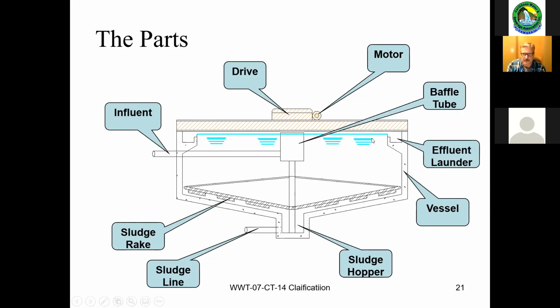And your baffle tube, which is in the center, disperses the flow. In a circular clarifier, there'll be notches in this baffle tube a lot of times. Sometimes this baffle tube is just below the water level, which allows it to flow that way, depending on the design.